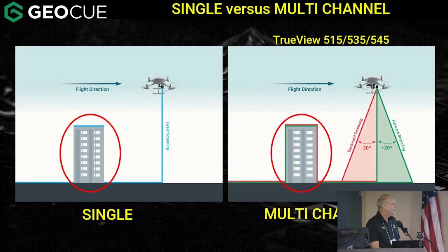If I have just a nadir scanner like this one, I will probably miss this part of the data. For forest, this is important because I can scan the trees at different angles, right? So you can see it creates different results in LP360. This really makes some difference when we're working with this kind of solution. You can see the difference between one and the other here.